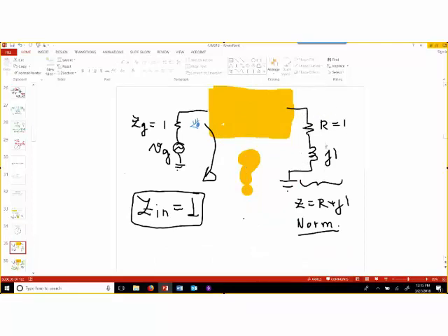Okay, so as far as the circuit goes, we have 1 plus j1, which would be a resistor in series with an inductor, and on the other side we have a generator. What do we have to insert here to see the complex conjugate of the generator, which is 1? What do we have to add so that, looking from here, the impedance Zin is 1?